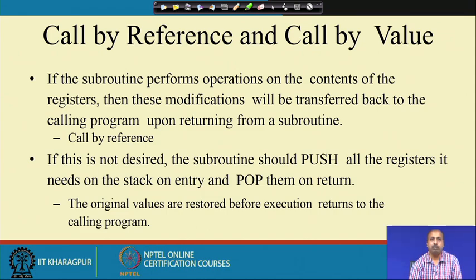Now, if the subroutine performs operations on the contents of the register, these modifications will be transferred back to the calling program upon returning from the subroutine. This is called call by reference, and if this is not desired, then the subroutine should push all the registers it needs on the stack on entry and pop them on return.